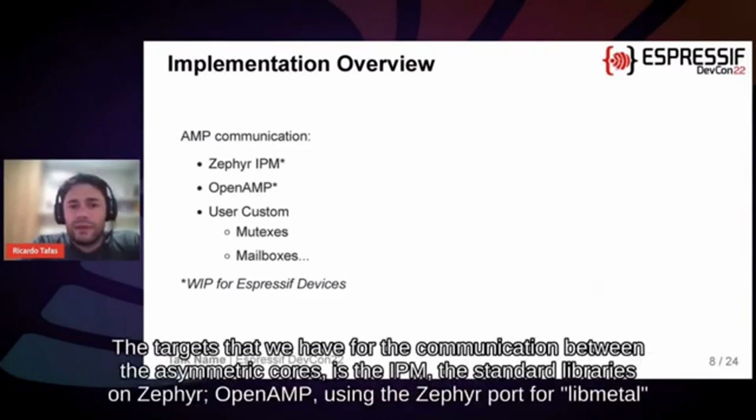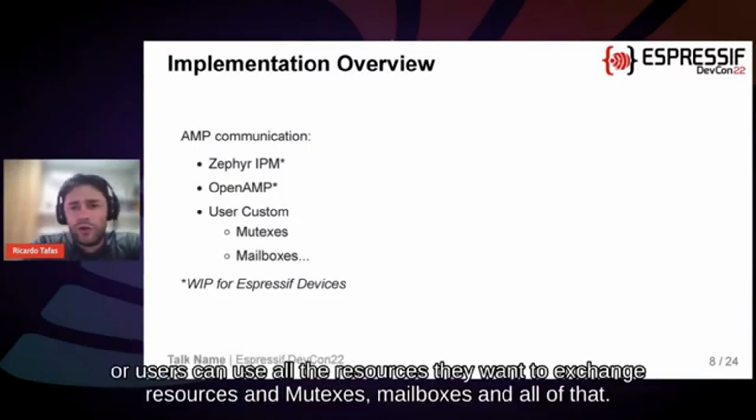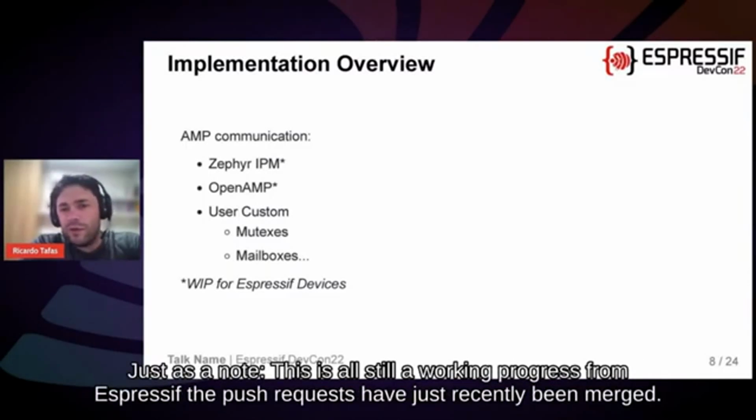So the targets that we have for the communication between the asymmetric cores are the IPM, the standard libraries on Zephyr, OpenAMP using the Zephyr port for LibMetal, or users can use all the resources they want to exchange data, and we have then mutexes, mailboxes, and all of that. Just as a note, this is all still a work in progress from Espressif. The pull requests have just recently been merged.